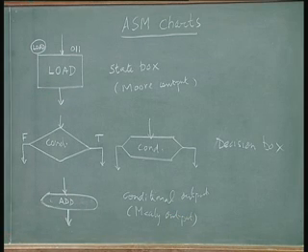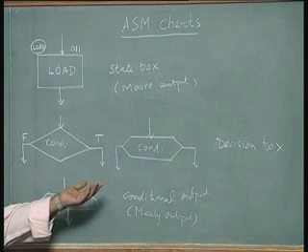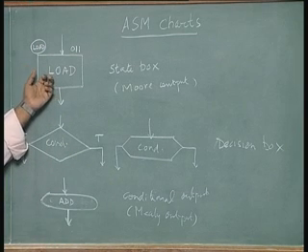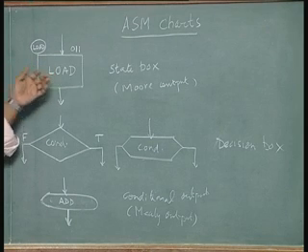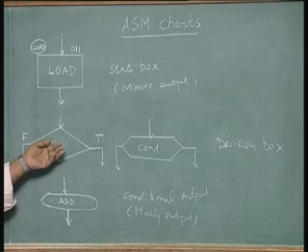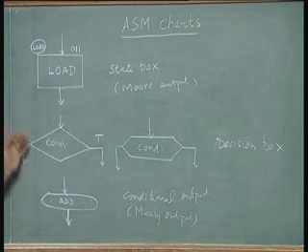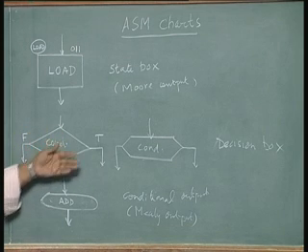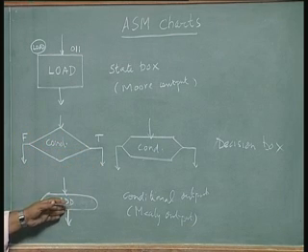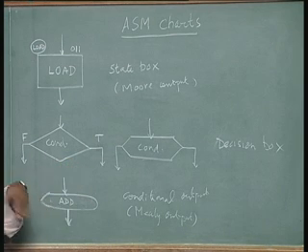So, these are three simple boxes, that is all. You can draw any algorithmic state machine by what is the state in which the circuit is, what is the signal that is to be tested at that time and conditions that will be tested in that state, what will happen if the condition is true, what will happen if the condition is false, and if the condition is true or false it goes to the respective next state. In so doing it may produce an extra output called conditional output, or sometimes it may not produce an extra output called conditional output. So, this is all there is to it in any algorithmic state machine.